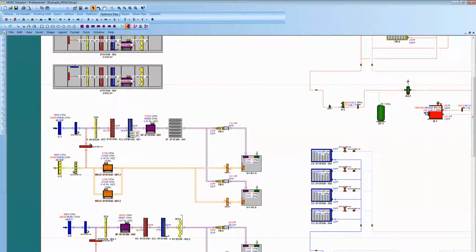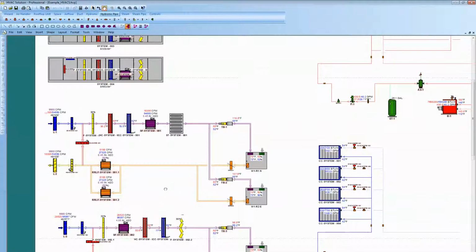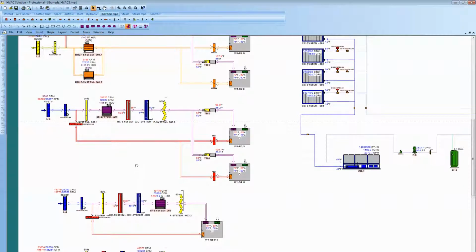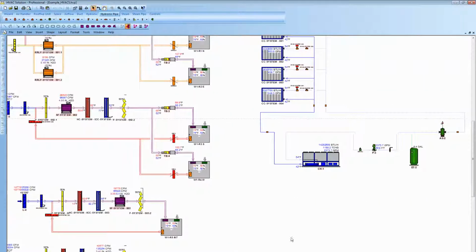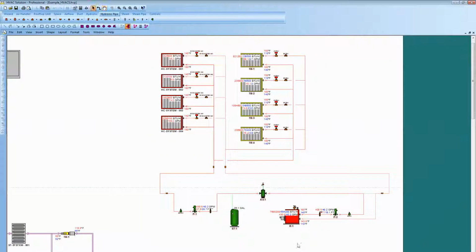Then down below is each airflow diagram, showing how the fans relate to the space and to louvers and dampers. Remember, we're going to size all this equipment and select equipment, so we need to know all that data in all the different components, louvers, dampers, spaces, so we can do selection of all this product. There's airflow diagrams there, and then over here to the right would be the hydronic cooling generation system and the heating. Now you can see these are the heating coils, and here's the reheat coils.